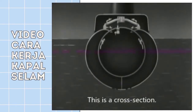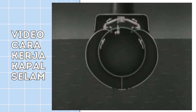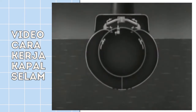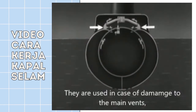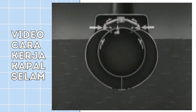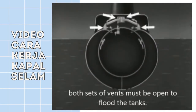This is a cross-section. The tanks have flood ports open to the sea. The main vent valves control the escape of air when flooding the tanks. These are emergency vent valves. They are used in case of damage to the main vents or to prevent accidental flooding. In order for the submarine to submerge, both sets of vents must be open to flood the tanks.